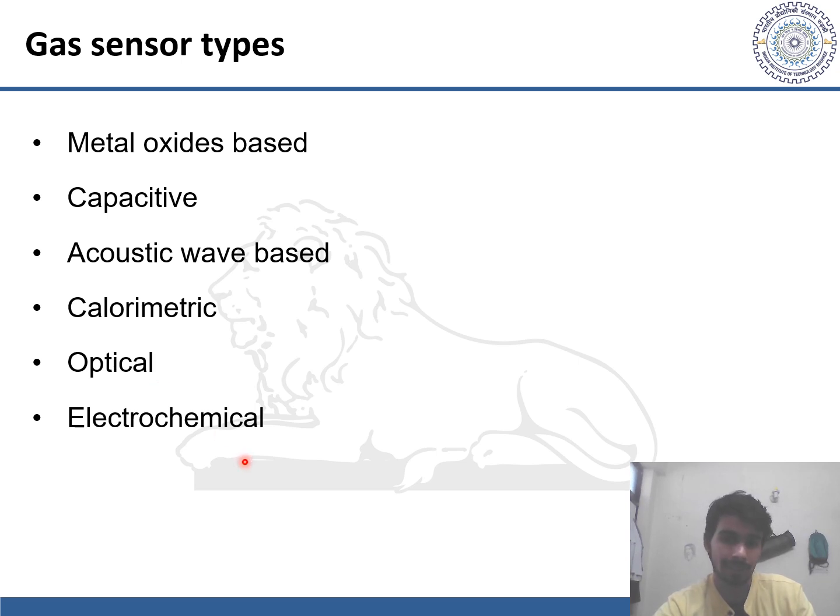In case of electrochemical, as explained earlier, electrodes present in the sensor react or might help in the reaction with gas, and the current produced helps in determining the concentration of gas. The reducible gases are accumulated at the cathode, while the oxidizable gases are accumulated at the anode. Oxidizable gases like carbon monoxide and hydrogen sulfide both are poisonous.